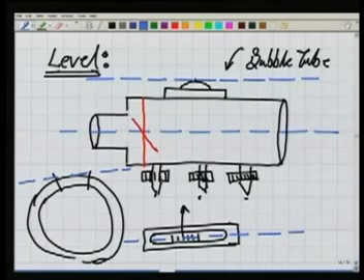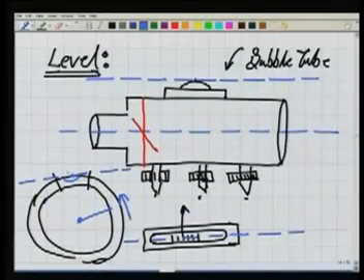For example, here that was the circular tube, so that's the line I am talking about, and this line we call the axis of the bubble tube. Now, because there is a little bubble here, if I rotate this tube, you can think that I am rotating this big circular tube. If I rotate it, this bubble will have a tendency to be always on the top. So this bubble will be at the top, as well as these graduations.